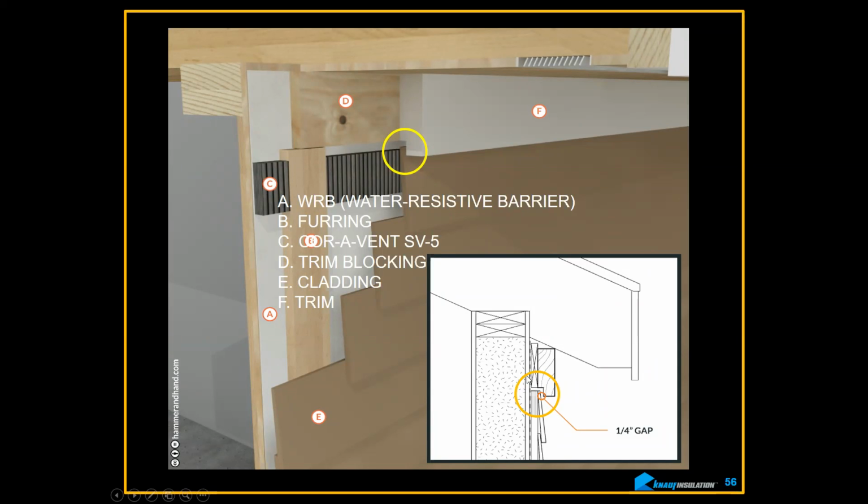This dash line here would be the weather-resistant barrier. But you need this gap, and you need moisture to be able to convect out. So right in here, you can see there's a little gap, and there's a little gap between here and here, which is noted right here. So any convection can go out here and also out here. So this is the detail you do.